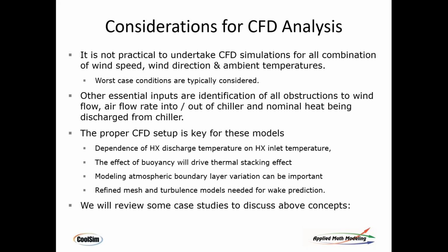To set these up correctly, you need to have the discharge temperatures and the inlet temperatures on the heat exchanger. HX, by the way, is an acronym for heat exchanger. So these devices are very sensitive to the difference between inlet and outlet temperature.